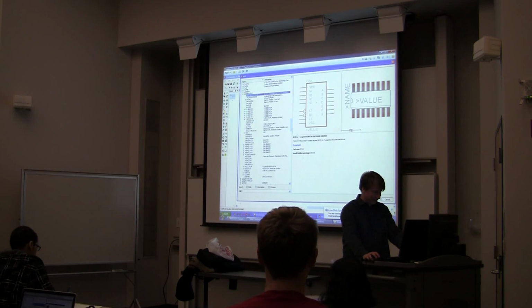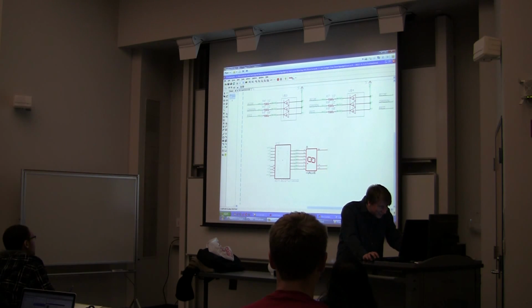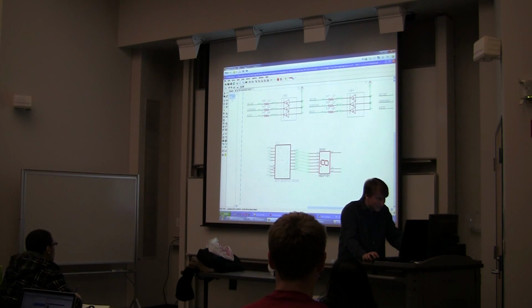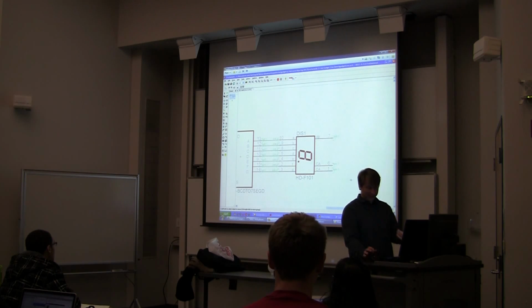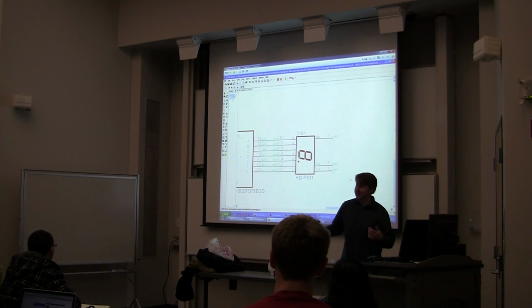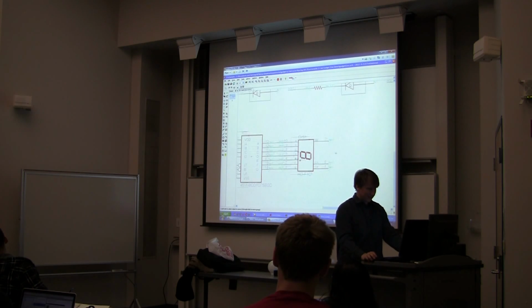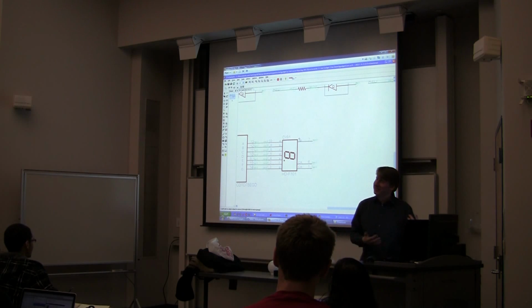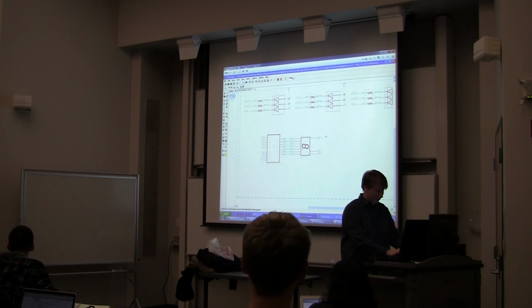Got that. And let's add in, lost it already. There it is. Is this crazy thing? Oh man, does that just light up? Oh, that's nice. Let's just do that. I'm going to do that to make sure the wires connect. So I've got my A, B, C, D, E, F, G's all hooked up. And you'll notice right here, CA. Again, it's common anode. So everybody expects you to have your LEDs hold high, and then you ground them when you want to drive them. So that, I think, is the decimal point. So alas, our BCD will not have decimal point technology. So that will just stay on top of it. All right.